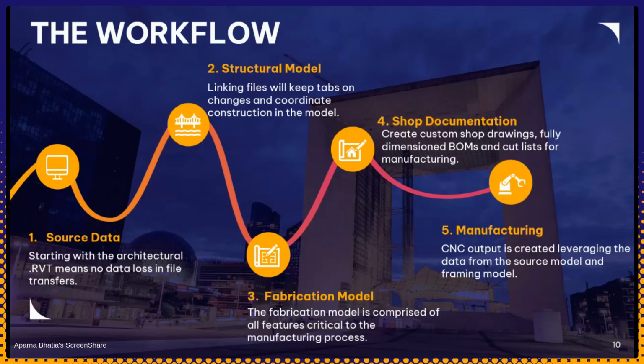So what's our workflow like? Since we are a Revit-based add-on and we use Revit as our main platform, Revit is a globally accepted tool and is widely used by engineers, architects, designers, and contractors in the AEC and manufacturing industry. Whatever your source model is, your source data is what you can use as your baseline to start your structural modeling. You can make that Revit model a linked file by linking in your structural model and your MEP files, all in one so that you can coordinate while you add in your framing.